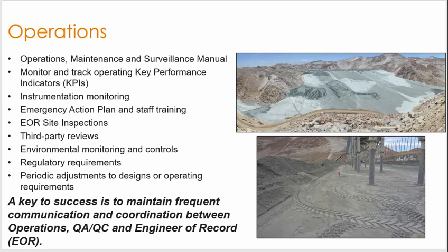One of those ways of tracking that is called key performance indicators, which would be things like the slope of the dam, freeboard, crest width, all of these different design parameters, and we would measure those on at least a monthly basis, and just make sure that all of our design parameters are being adhered to as we set forth to do.